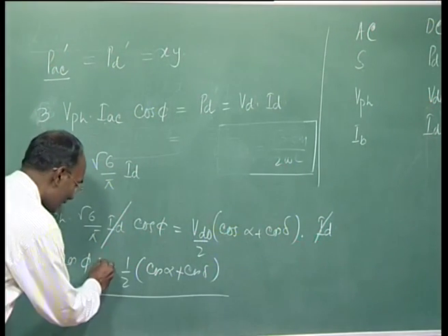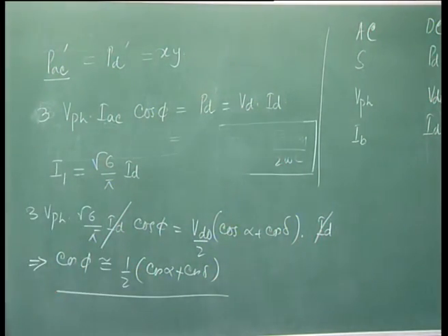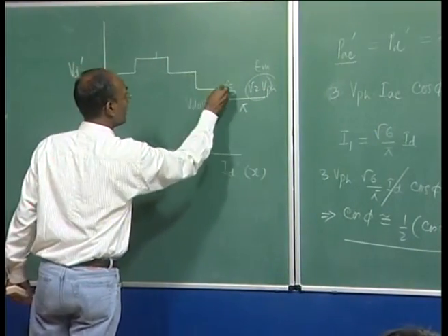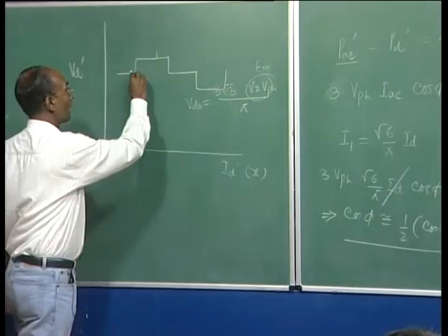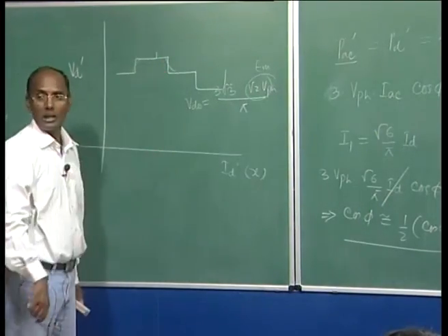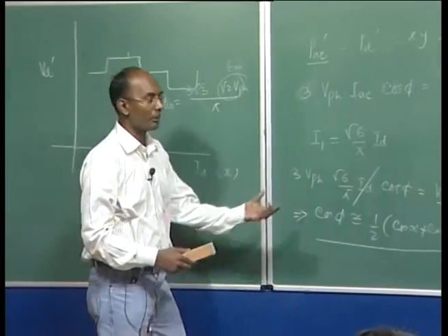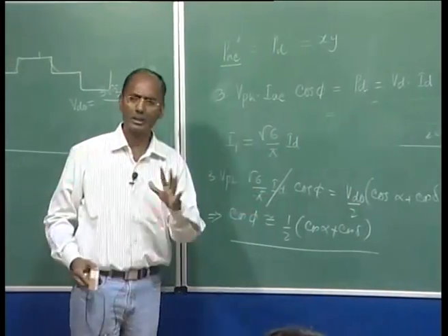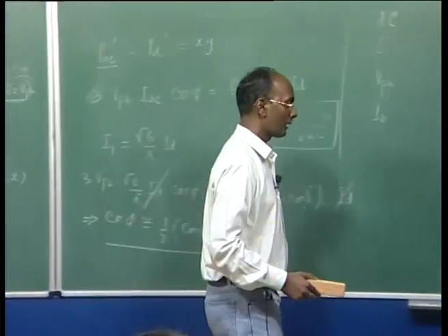That's why I can say this is approximately equal to this value. Remember, this value we derived in the ideal case when the current was changing like this, if you remember. But due to the overlap, this will be changing. And due to this change, this current fundamental component will also change. This will affect, and the error is very small, and finally we can get this expression that is approximately equal to this value.